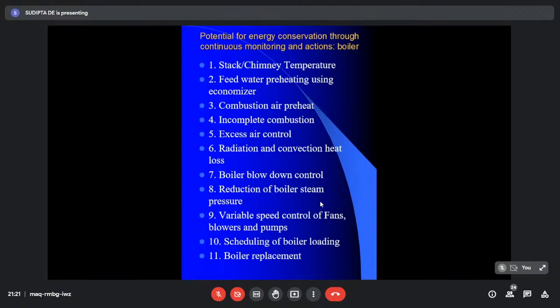But unfortunately, that was the previous practice in power plants. Not only in power plants, in process plant boiler operation, earlier the process was, whenever there is a low load, you just vent out a certain amount of fluid, maybe air, maybe water, but keep the fan speed or the pump speed or the boiler speed constant. That was the convenient process. But now people understand with load variations, if you can make a variable speed drive and control the speed, then whatever energy input you give does not get lost as a bypass. So this is now very much mandatory in power plants as an energy conservation measure. Anyway, with technology development, this is also possible now.